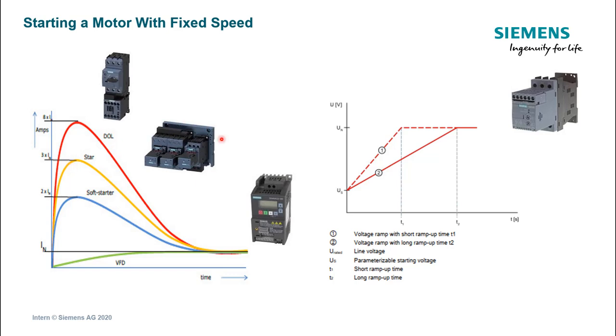These are typically used for heavy duty startup motors, for example lathes, milling machines, saw blades, bandsaws, applications of that nature. They can typically draw 3 times the rated current. That is a reasonable amount of starting current, but this is also classed as an older form of technology.